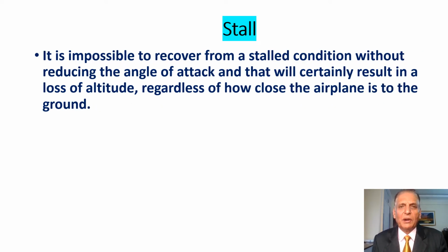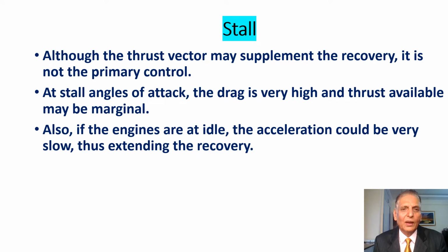It is impossible to recover from a stalled condition without reducing the angle of attack, and that will certainly result in a loss of altitude regardless of how close the airplane is to the ground. Although the thrust vector may supplement the recovery, it is not the primary control.